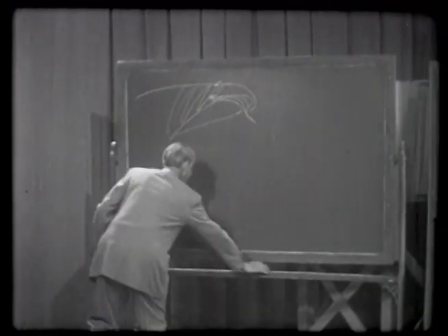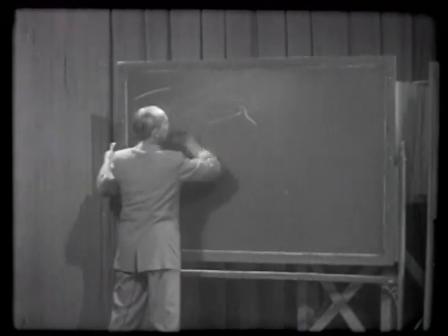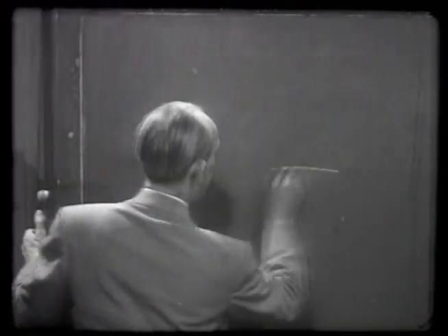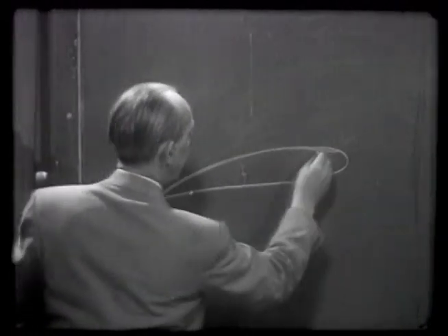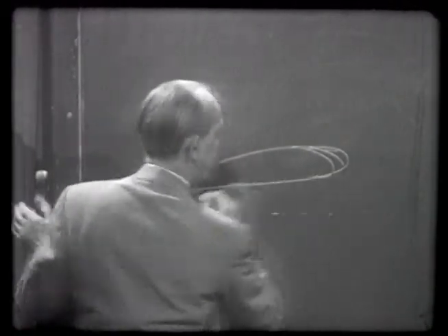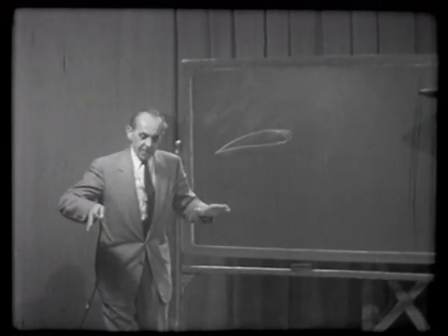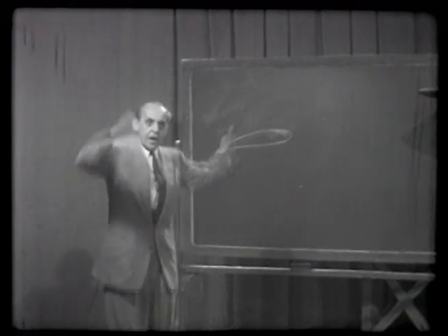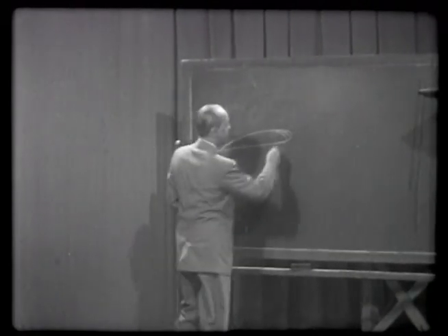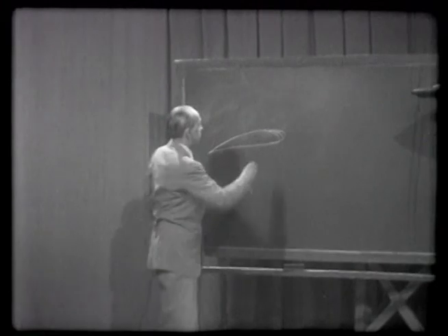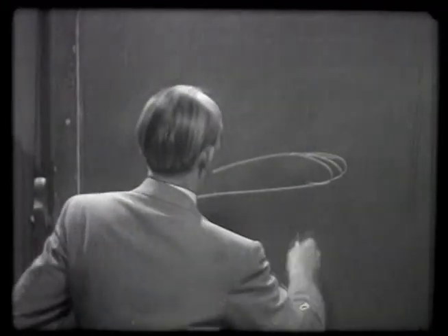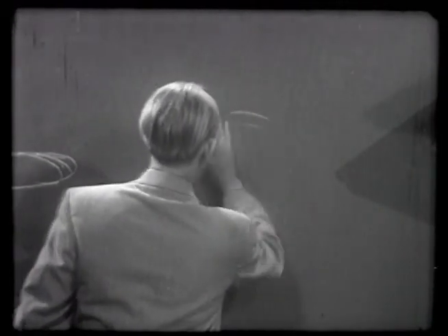Now, this method of having a slotted wing is not only used for preventing the stall on the nose, as you see it on fighter wings, for instance, used to prevent the stall when you make a tight turn and you have a kind of automatic slot which kicks out when you have this high angle and prevents the stall.